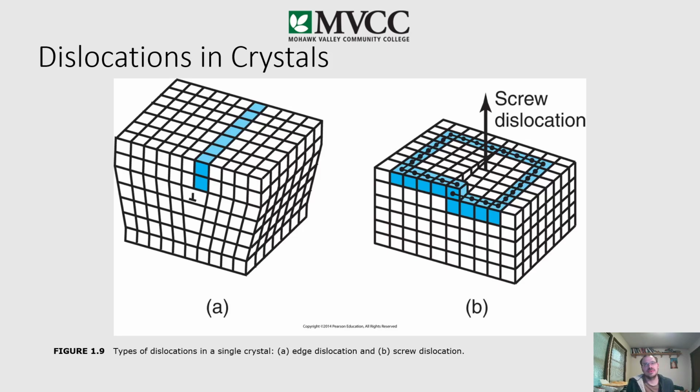So what do those defects really do? Well, you look at the crystal again, in this case in 3D fashion, and we have dislocations in the crystal. This dislocation could be due to, say, an extra atom being shoved in there or a missing atom. You get this structural pattern because an atom bonds with an atom, which bonds with an atom, and so on, right? You get that BCC structure. Well, in this case, either one is missing or one gets added, so you get a defect essentially in that crystal structure.